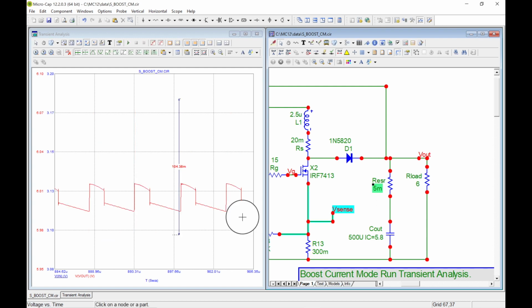Okay, spinning wheel, and then look at that. Look how much it dropped, and it looks much better. So that's why you want low ESR caps on your output. It looks big because we're zoomed in on this, but it's not too bad actually.